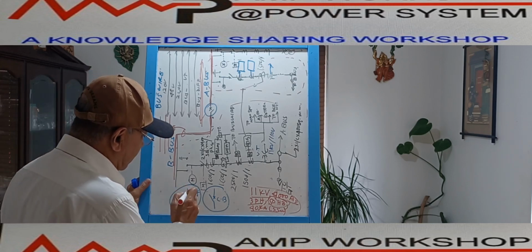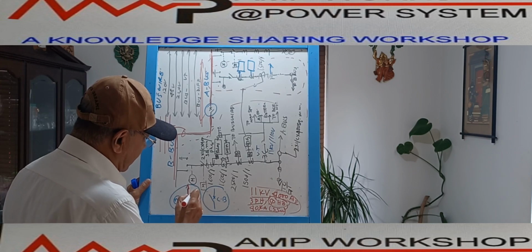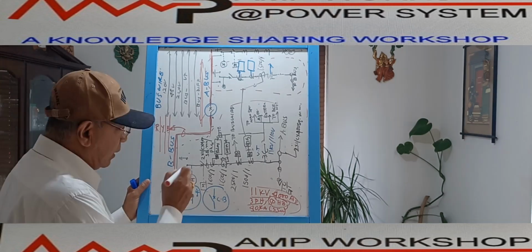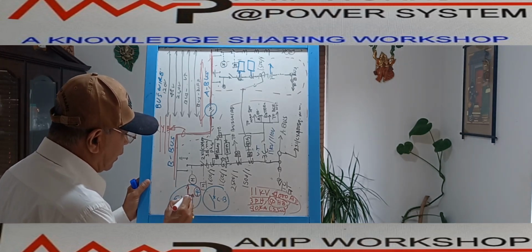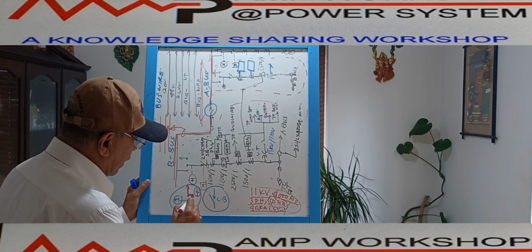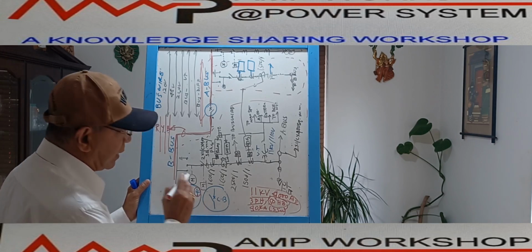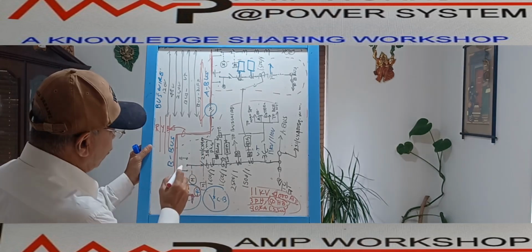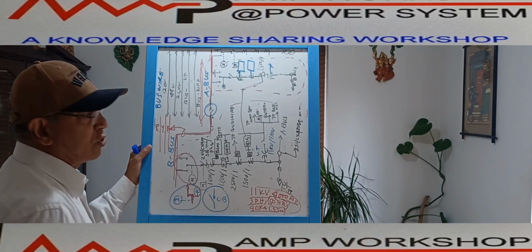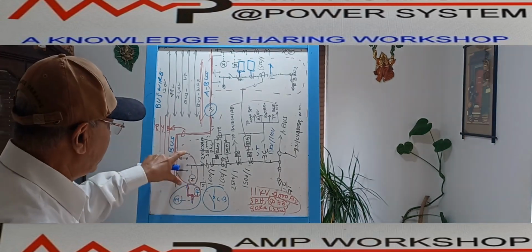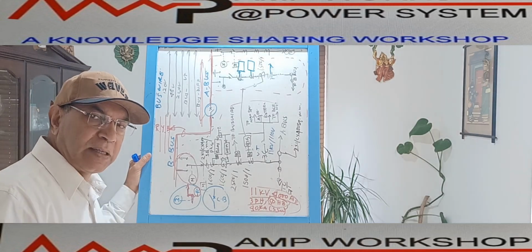This is going to the bus side connection, then this is your driving rod, and then this is an earthing position. When this is connected over here, then the disconnector is connected. When this is connected over here, then the disconnector is grounded out. That is what we are showing over here. That is first our disconnector, and this disconnector is motor driven. That is the disconnector.